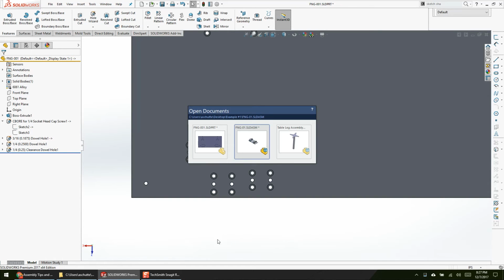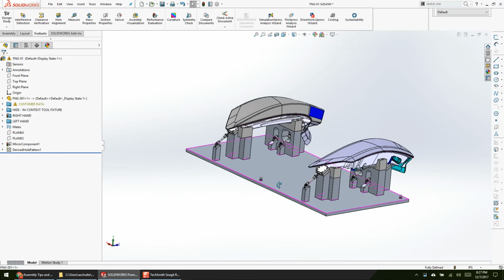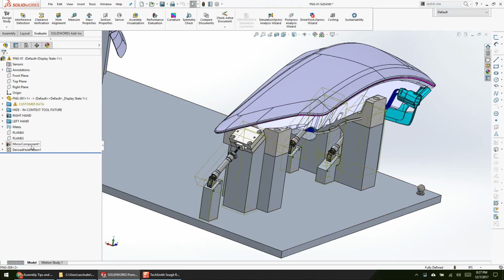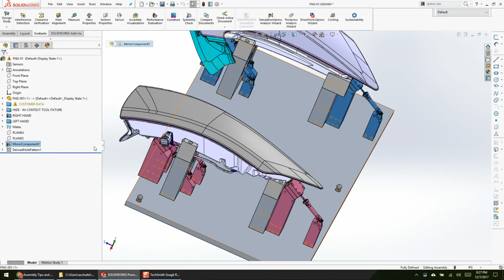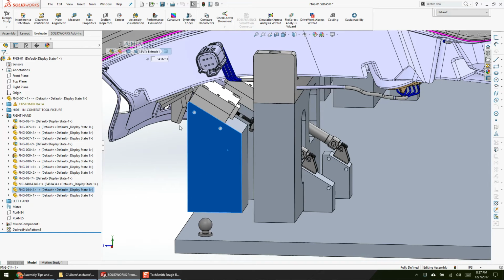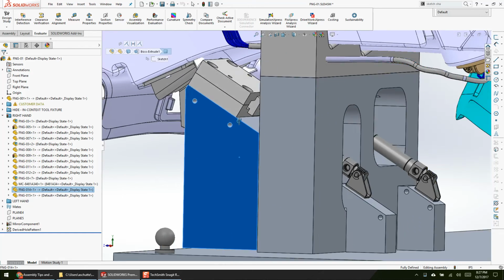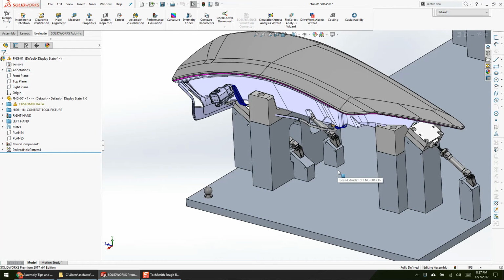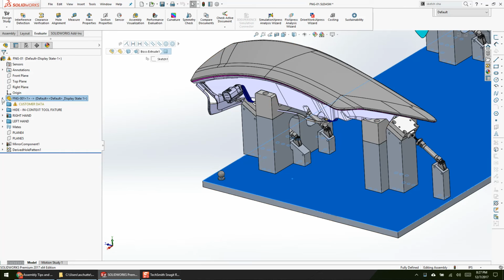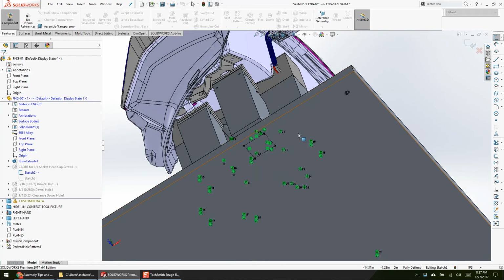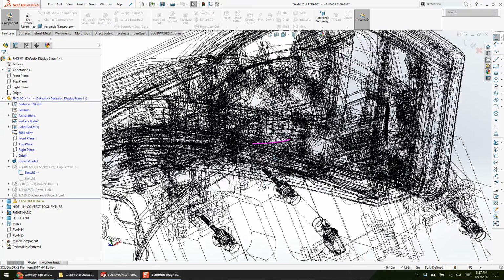And the reason this is awesome is because other than fillets, you put in holes last. So I designed, I don't remember which one's mirrored. Okay, so here, the right, yep. So I designed all of these on the right hand, and this is a mirrored part, mirrored automotive part. So all of these parts I designed on the right hand side, and then I mirrored them over to the left, and every hole in this plate, so these holes here are all tied to, oh, that was a mistake.